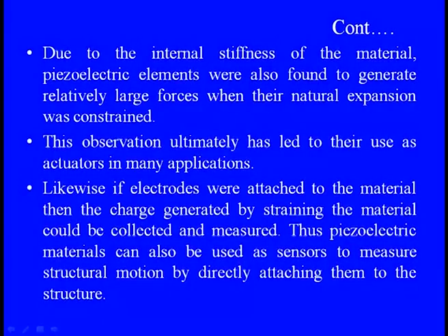So these piezoelectric materials can act as actuators, and at the same time, if electrodes are attached to the material, the charge generated by straining, from the force, pressure or stress applied, can be collected and measured. So the piezoelectric material can also be used as a sensor to measure structural motion by directly attaching it to the structure.